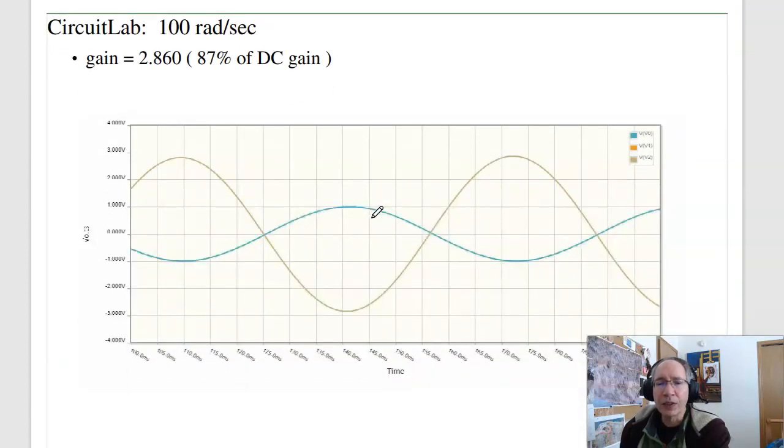If you go into lab and build it, it's kind of harder to sweep gain versus frequency, but what I can do is apply a sine wave in and measure the gain of the filter at that frequency. The 2 points you definitely do need to check are the requirements. At 100 radians per second, I need to make sure the gain is less than 0.9. Again, that's 0.9 of DC.